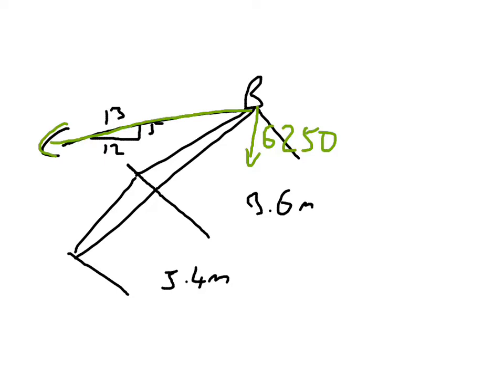We've also got the weight of the arm itself. So the weight of the arm itself with the boom was 3,250 newtons. It's given you point G, so point G is somewhere about here. And it's asked you to draw your free body diagram, so we are missing 2 different forces on here. We're missing AX and AY. And that was it, that's your free body diagram